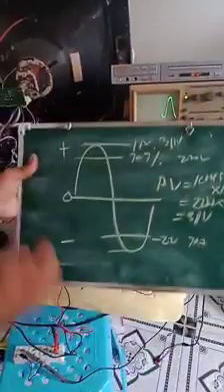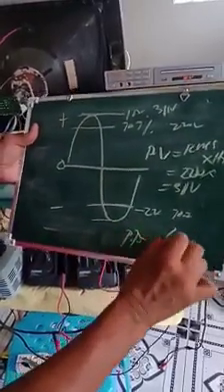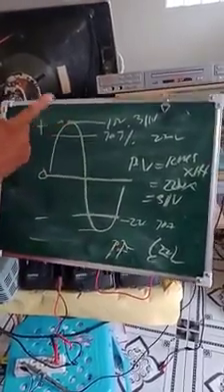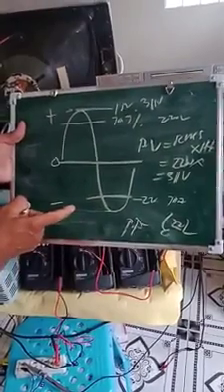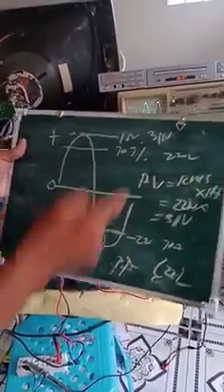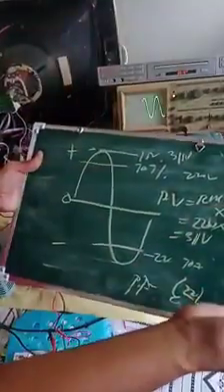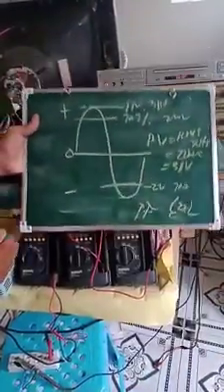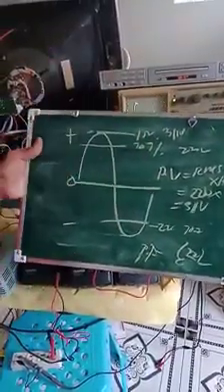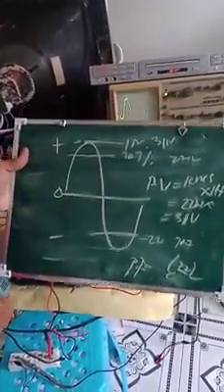Remember, the peak to peak is around 622 volts. Because the peak to peak value is the peak of the positive alternation and the peak of the negative alternation added together, the sum is 622 volts. Right? 311 plus 311 is 622 volts, the peak to peak value being distributed. But what is measurable is only 220, which is only 70.7% of half of the cycle, or one of the amplitudes, positive and negative amplitudes.